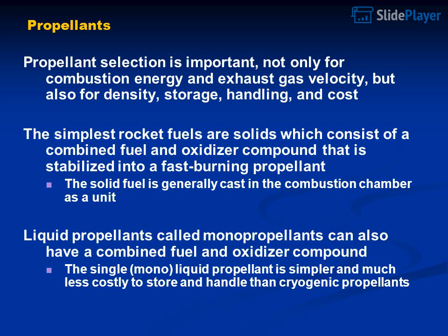Propellants. Propellant selection is important, not only for combustion energy and exhaust gas velocity, but also for density, storage, handling, and cost. The simplest rocket fuels are solids, which consist of a combined fuel and oxidizer compound that is stabilized into a fast-burning propellant. The solid fuel is generally cast in the combustion chamber as a unit.